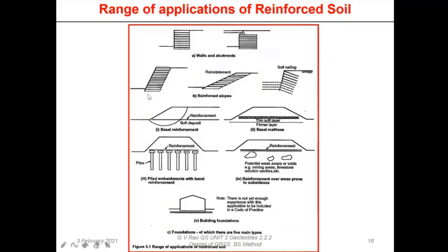And then we have a slope, which is built from the beginning. And also we can build steep and shallow slopes. And this could be also reinstatement of failed slopes. So that means failed slopes in the hilly regions, it may happen. And then even soil nailing, wherein we are going to start reinforcing. As we keep cutting down, we start reinforcing, but these are different kinds of materials, nailing. But in the other case, we are constructing from bottom to top. Everything is from bottom to top.